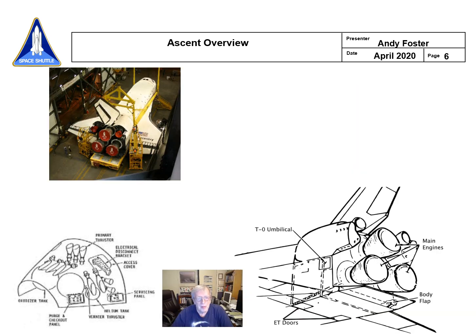And so here's a picture with the orbiter, and you can see the main engines on the back that we talked about. Right back here, they put out about 470,000 pounds of thrust each, and they get fed through big feed lines. I'll show you in a minute on the external tank through these two, what we call umbilical wells right here. These are E2 doors. They're open, of course, so you can get to the big feed lines when you put the orbiter on the tank, and then once you jettison the tank, they close up because you have thermal protection system tiles in the bottom.